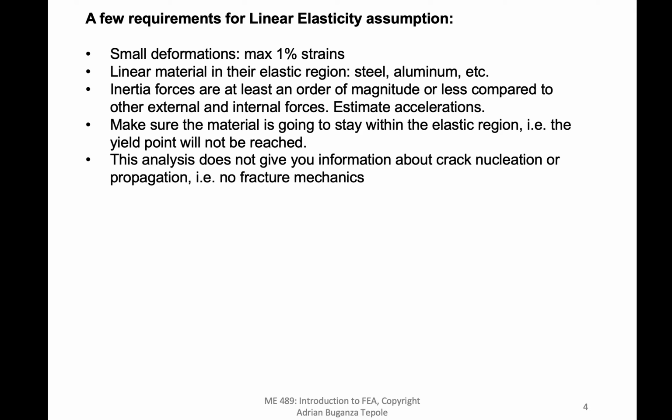Another one, and this is similar to the point about linear materials, is staying within the elastic region of the material. Make sure that the material is going to stay within the elastic region, and therefore that the yield point will not be reached. The moment you go beyond that, you start to have damage or plasticity. And what we have covered in class so far is not enough to represent that.